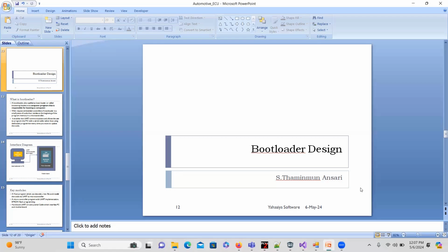This bootloader is a small, straightforward program which will receive the executable from the outside world using a communication bus system. The communication bus system can be CAN, RS-232, USB, I2C, SPI, whatever it is. You can receive the executable to be flashed via a communication channel.